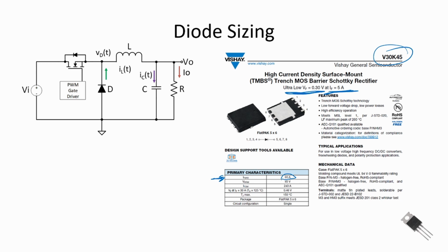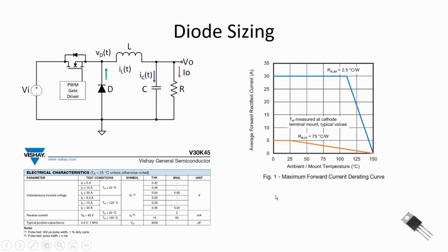The other good thing about Schottky diodes, I do not have to worry about reverse recovery. It's a majority carrier device. And so we don't have the recombination of holes during the turn off phase of this diode. So again, fast, no reverse recovery losses in Schottky diodes. And this one's going to work pretty good. But I want to come back to this 30 amps and this 5 amps and see what's going on with this device. So here's more from the data sheet.